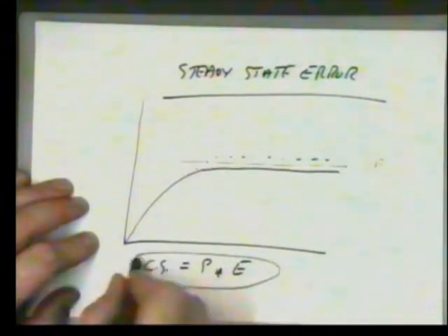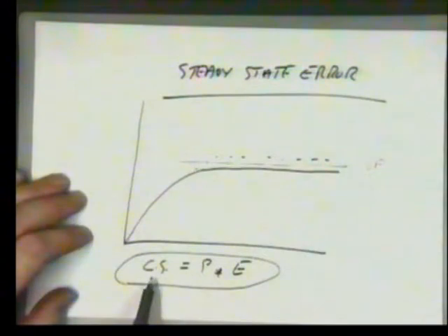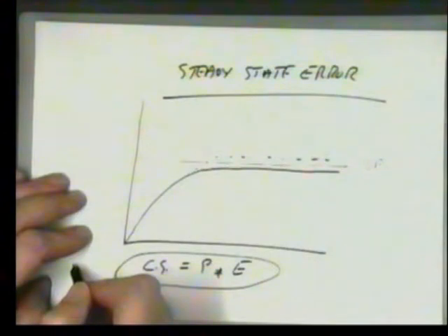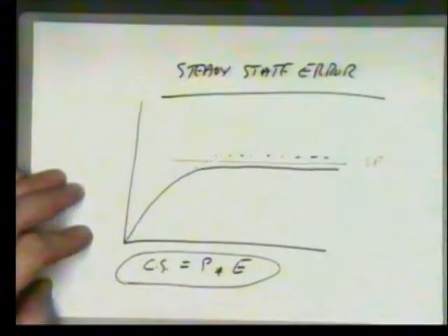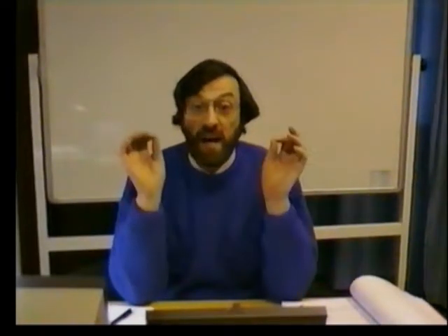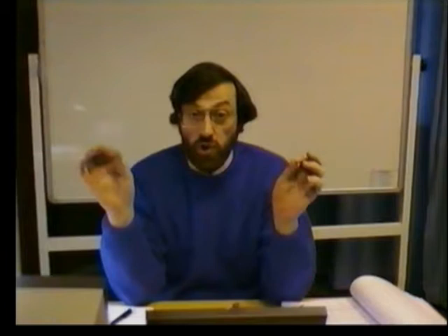That is if you use the proportional control structure. Control signal equals some constant multiplied by the error. Why? Because that error isn't the error now, it's the error from some time ago, and things have moved on and got worse. So you always have a steady state error in a truly proportional system.